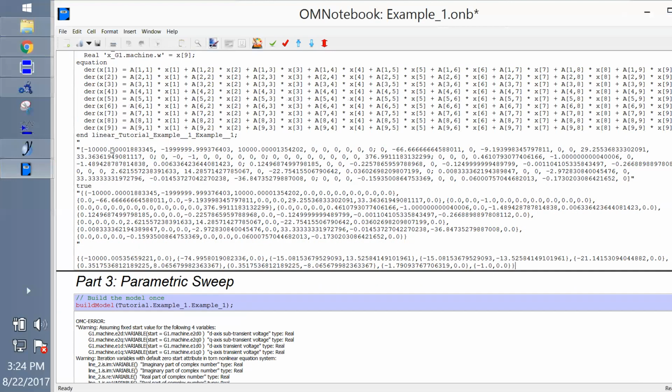Just the software we are using, OpenModelica. No, the OpenIPSL. Yes. So will it work with other Modelica tools? Modelica, JModelica, and OpenModelica. I am still working in my free time to make it work with System Modeler, but it's their fault. I'm in contact with them because their compiler does not initialize it correctly. Well, what is the best commercial? They all have their plus and minus. So you have options. You can try all and see what you like for your particular task.